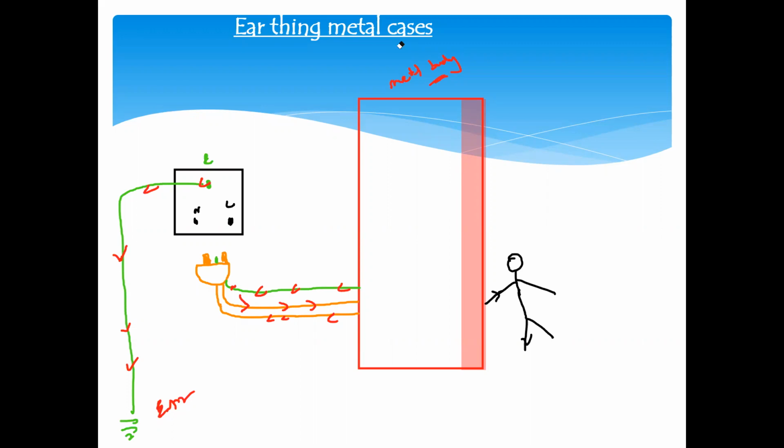Normally, mobile chargers also provide you a 3 pin plug, but that third pin is just to fit in the socket. That third pin is made of plastic and has nothing to do with earthing. It is just for plugging in the device. It's not working as an earthing, because a mobile phone is not drawing too much current from the circuit.